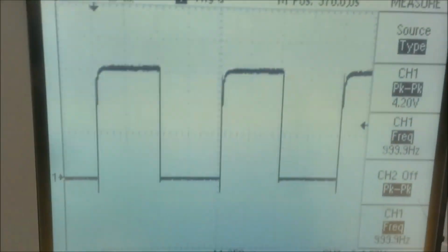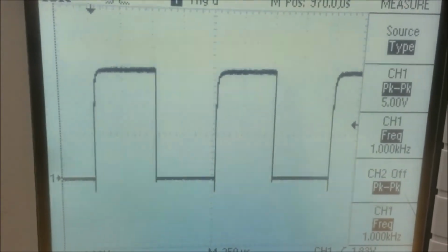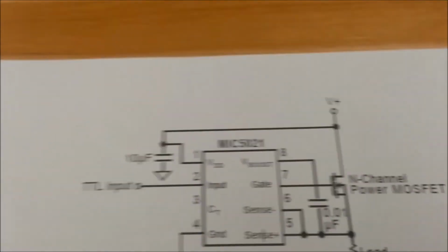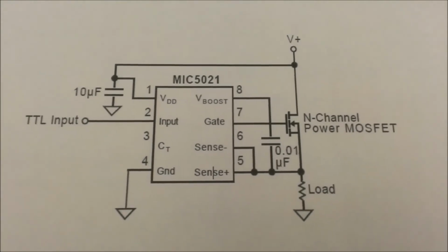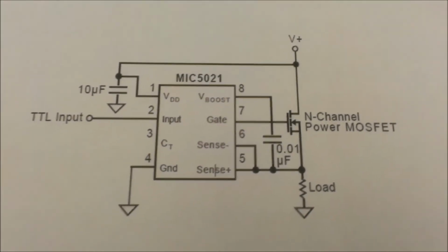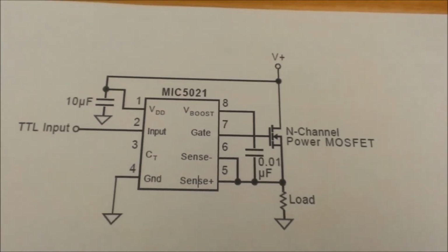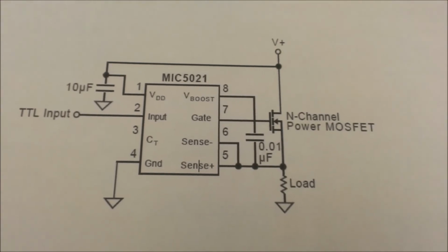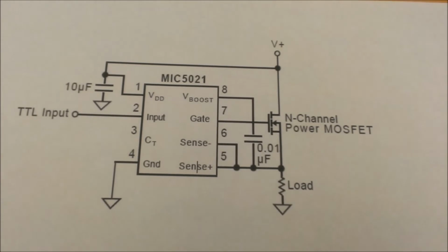To the oscilloscope. You're viewing the wave of VDS, and this proves that the MOSFET is switching. Just to make our last points known, high switches are needed for different applications. This circuit is much better because it only uses one power supply. It's not as expensive as the low side driver with the high side switch would be when you have to use two power supplies and separate the grounds for it to work.